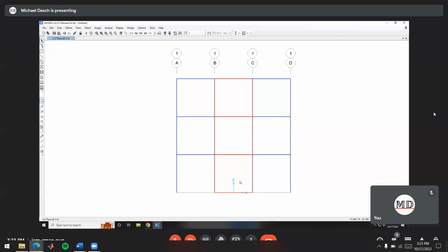Okay, so next thing we want to do is mesh our plates here. Right now, the model is considering these as just one big object. Going a little bit behind the scenes in how the math works for finite element models like this, when we have shell and plate elements, there's some assumptions we make in the calculations that aren't necessarily true under all loading circumstances.